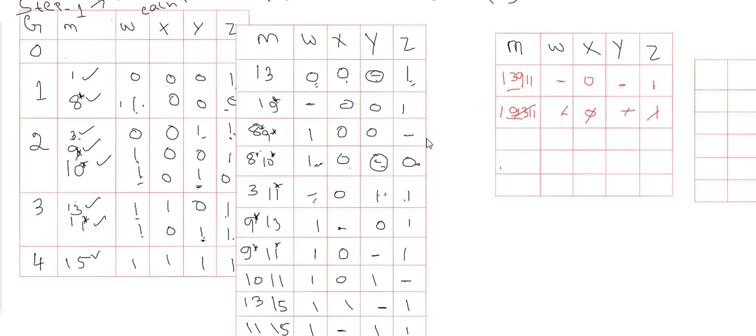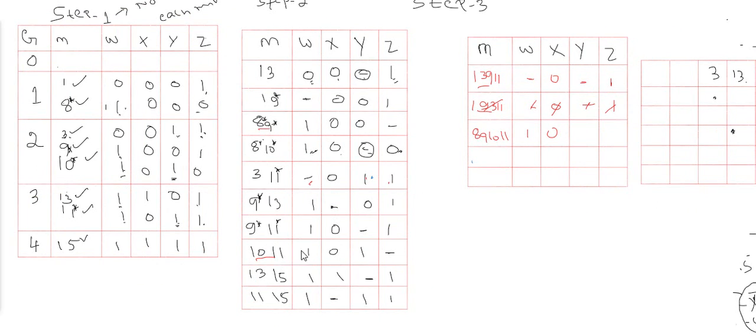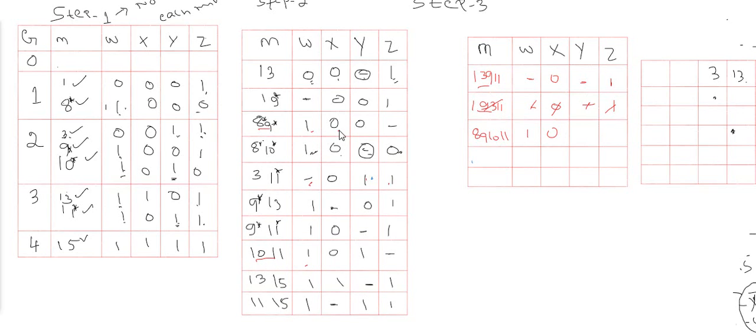So we will move on to 8, 9. In 8, 9, the dash is present in z and w is 1. Check anywhere the same dash 1 is present. Yes, 10 and 11 also present the same. So go to 8, 9, 10, 11. In the grouping of 8, 9 and 10, 11, the first position is 1 in both. Then it is 0, and that 0 is also the same. In the y portion only it changes, 0, 1. So we have a dash here, and the last bit is anyway dash.